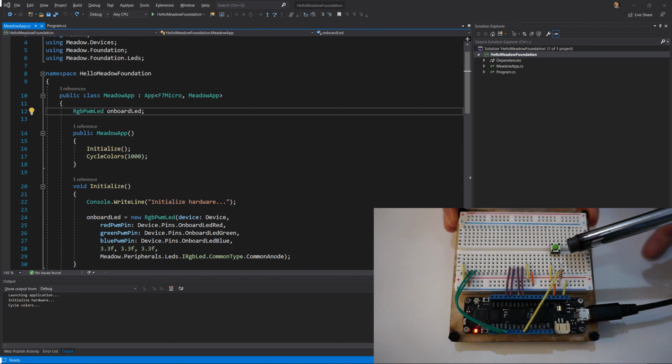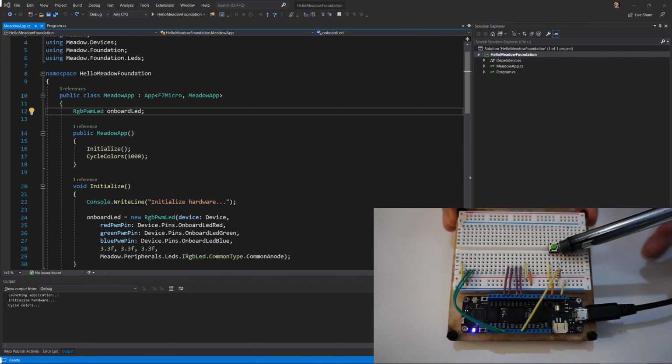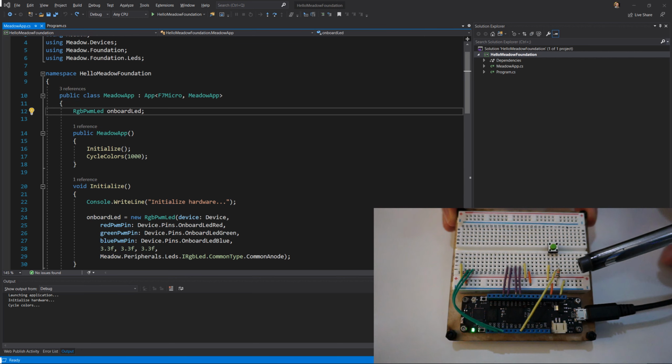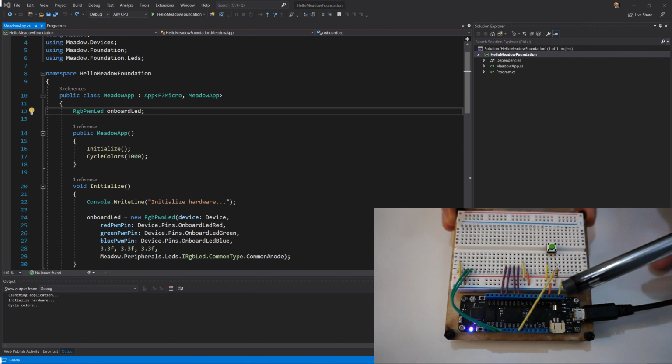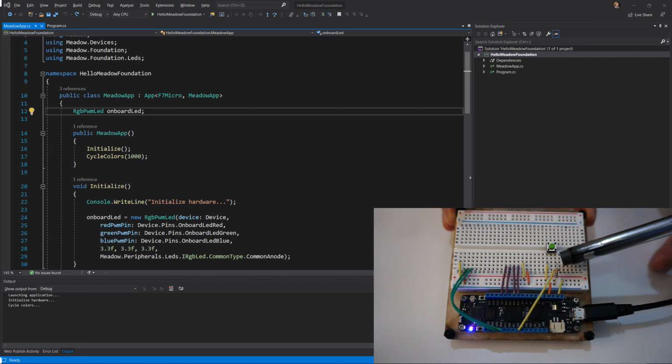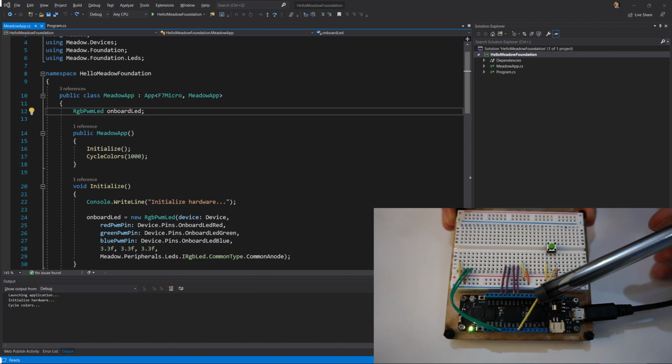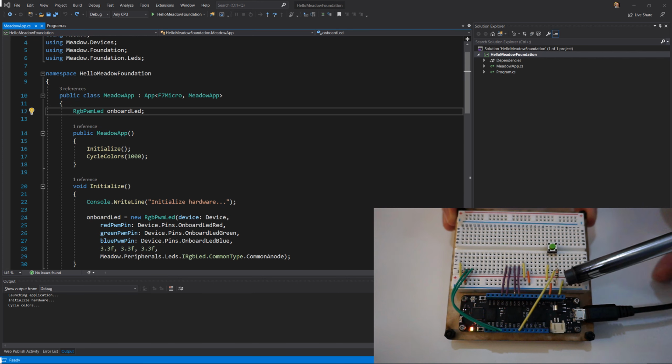So first, if we look at our button, notice it up here. If we follow it down, notice there's a resistor here, and that resistor is connected to ground. Now, just below it, and again, I'm not sure if this is super easy to see in the camera, but this long jumper wire here is connected to the same column of pins as the resistor. And so what that means is these are all connected, and so that resistor is connected to this jumper wire, and they're both connected to ground.